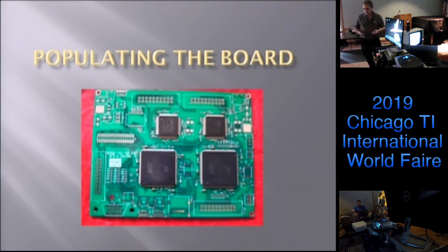The neat thing about the reflow soldering machine is that it will ramp up the temperature. Basically, you put solder paste on a board, and you do that through a stencil, and then the solder paste is kind of tacky, so it will hold the components in place. Then you use hot air from the bottom and the top of the board to preheat the board to a certain temperature, soak it a little bit, then ramp it up to a critical temperature where the solder flows, and then the temperature ramps back down rapidly so as to not damage the components.